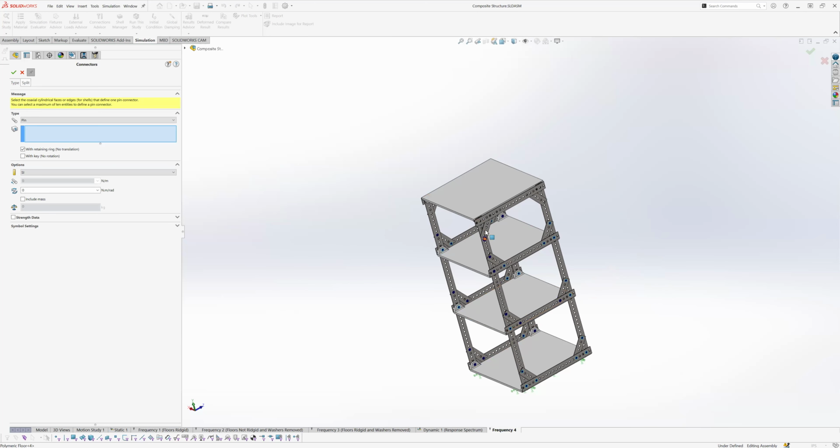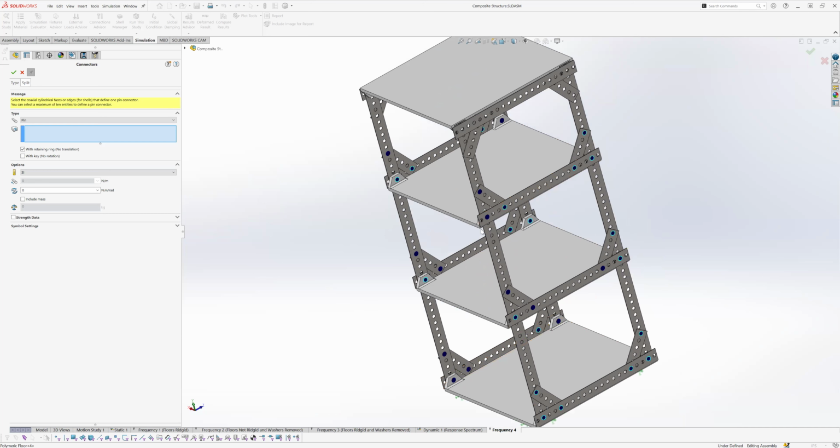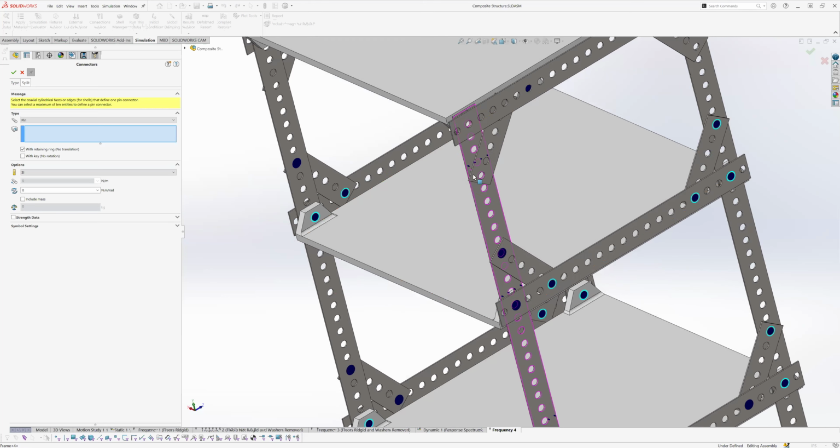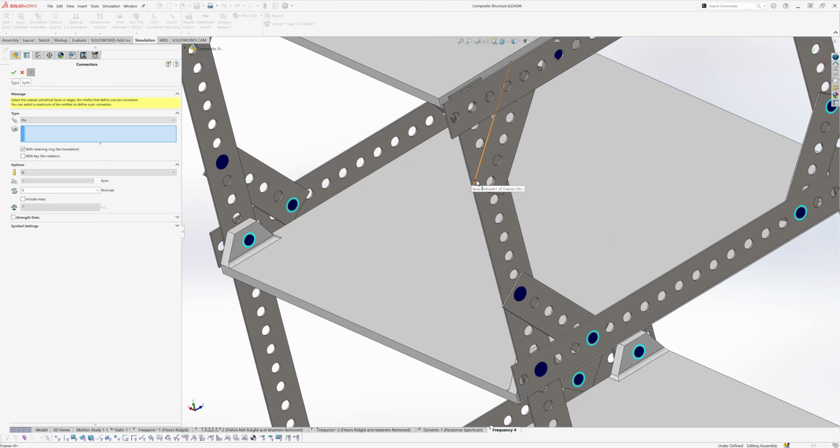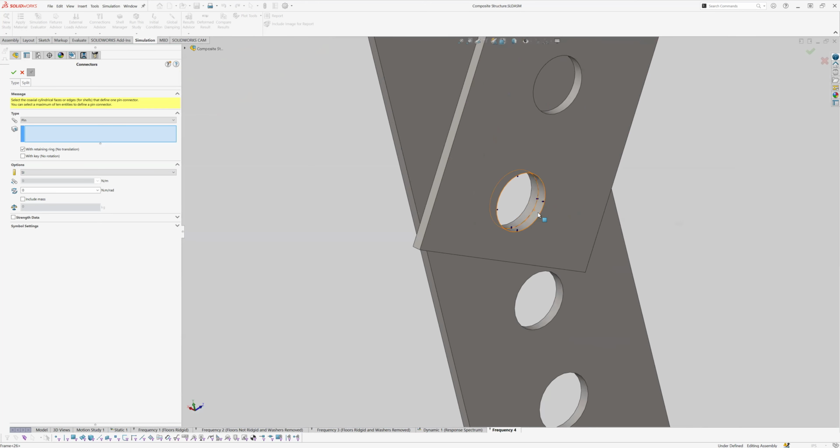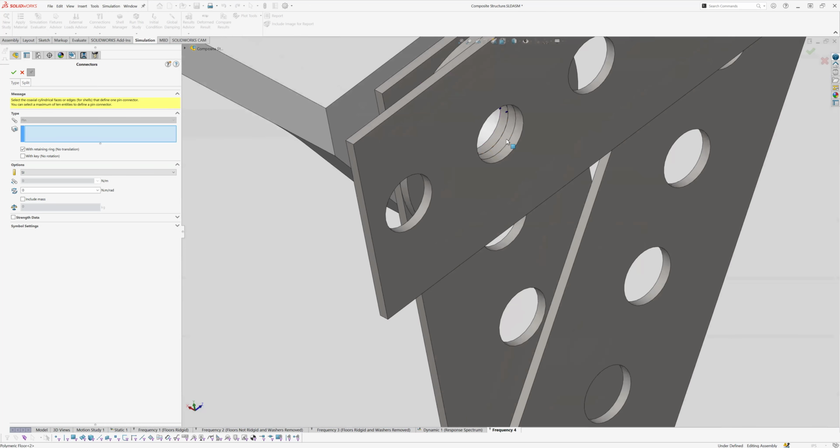It's giving that error because I have 2 cylindrical faces up here, and the other 2 were selected probably down here somewhere. So it's saying that it's impossible to put a pin through 2 sets of cylindrical faces that are not concentric. So then we'll start again and hopefully that'll fix that issue. So here, there we go. 1, 2, 3, 4.